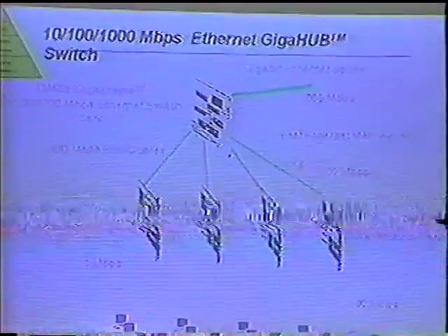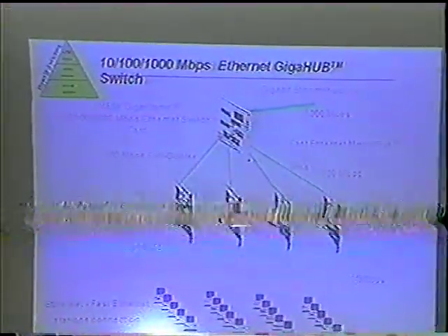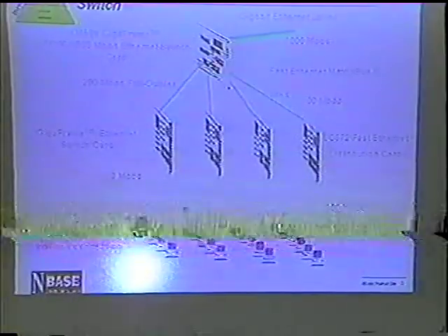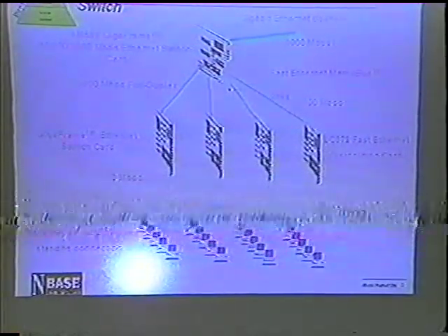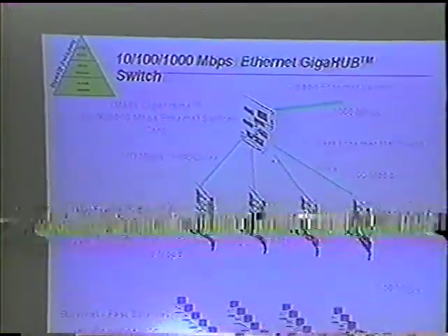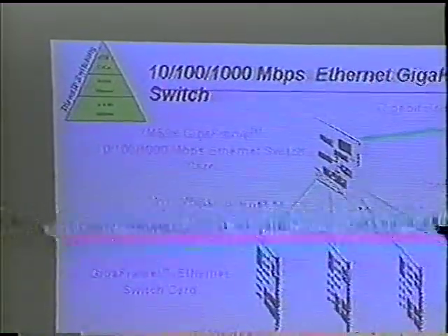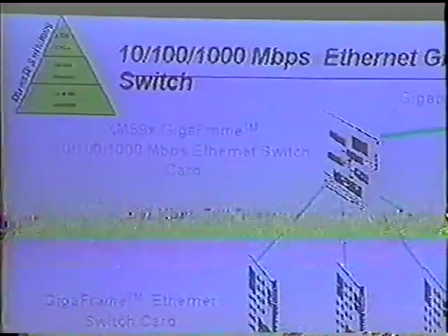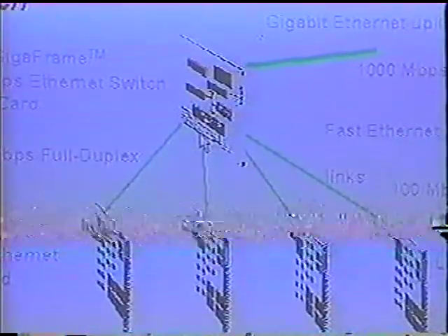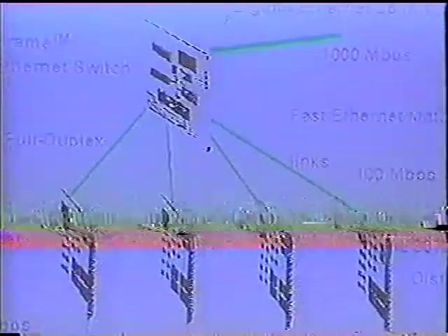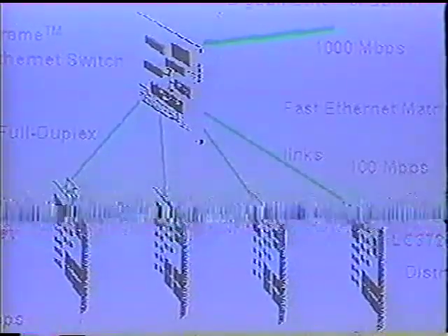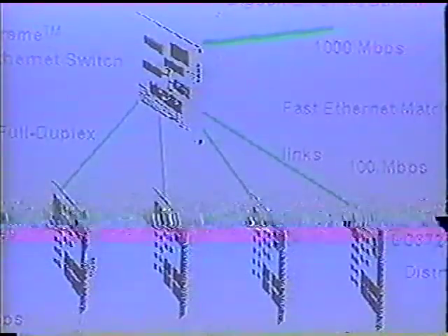So first I would like to concentrate on the Ethernet switching system, because I think this is the major functionality that we give in the Gigahub, and it shows the most powerful side of the Gigahub. A classical configuration of the Gigahub is to have one powerful switching card with a lot of 10/100-base ports, and this powerful card is connected internally through the matrix bus to additional switching cards.